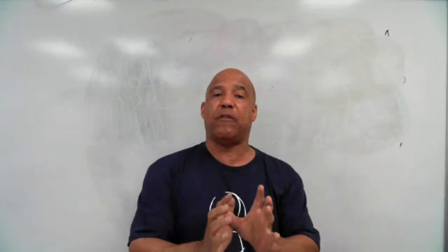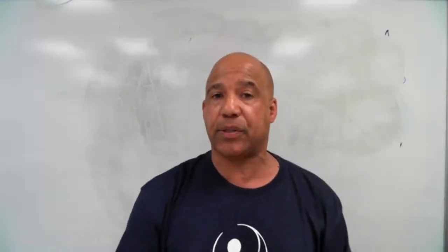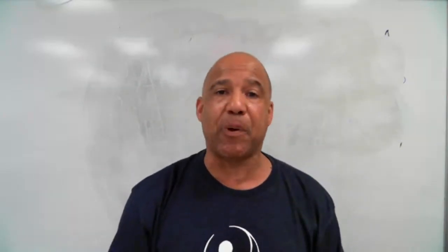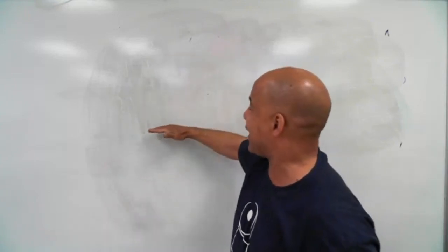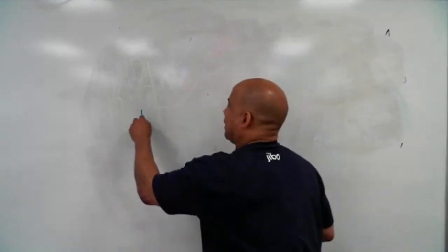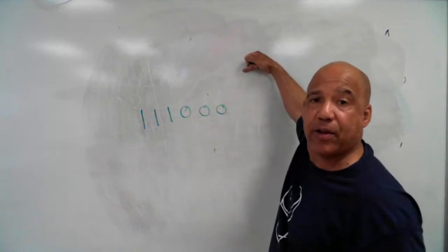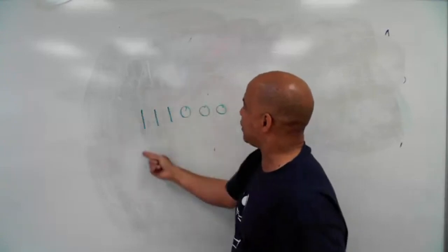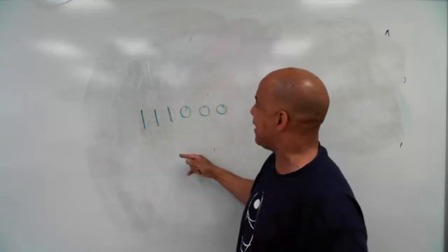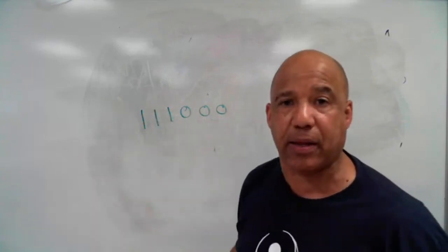So the big problem with analog signals is that if you make a copy of a copy of a copy, the signal quality degrades. That does not happen with digital, because with digital, you're not storing the actual signal, you're storing a code. You're storing a group of zeros and ones that represents a certain value. So if you were to play this back, these zeros and ones determine what data point you're getting back, and this 11000 is the same no matter how many times you repeat it.